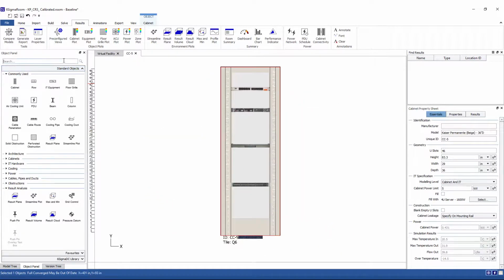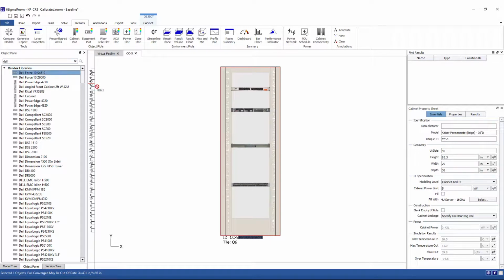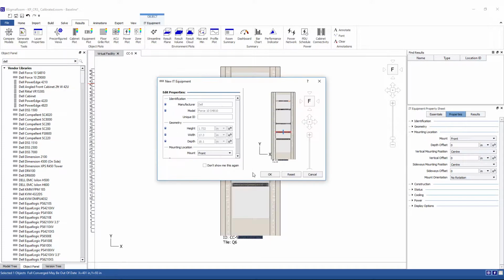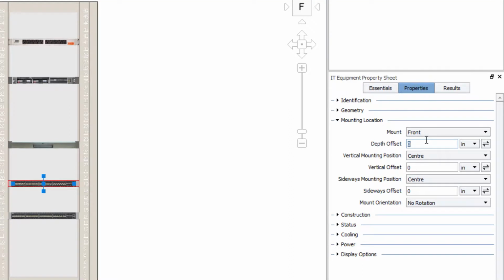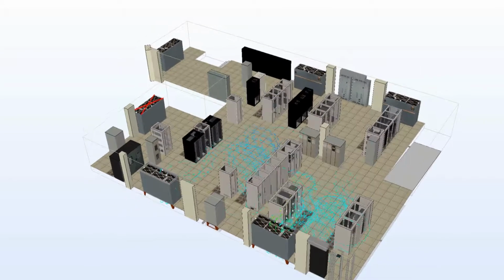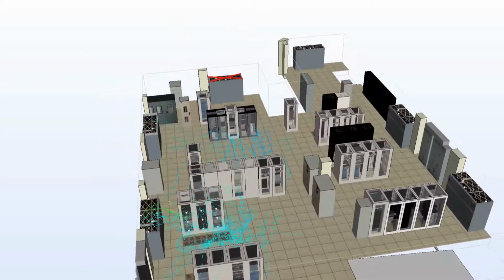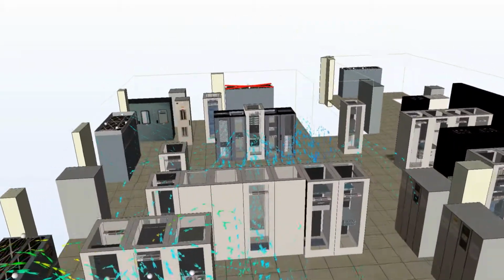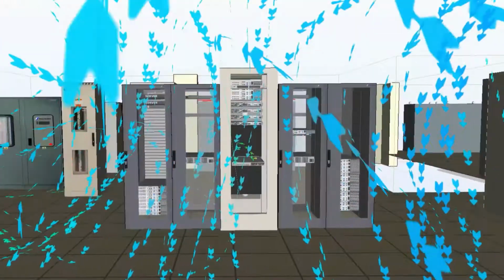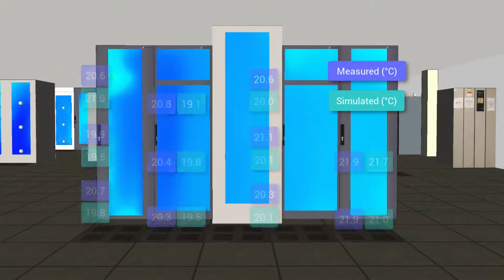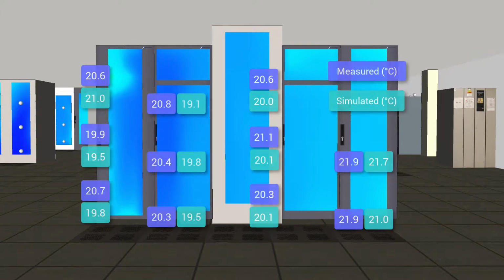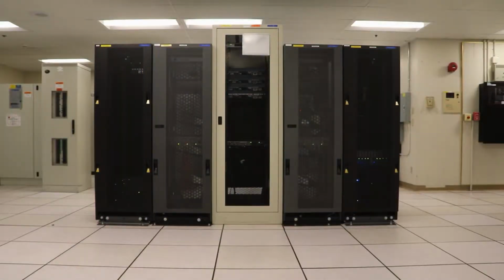Our engineers then continue to refine the model through additional iterations in a process called calibration, which uses the measured data to check that a model is representative of the real facility. Where discrepancies are not obvious, we investigate further, often uncovering deviations from design or unknown operational issues. When the process is completed, we can use the model to recreate power and cooling system operation and highlight areas in the live facility that need improvements or changes.